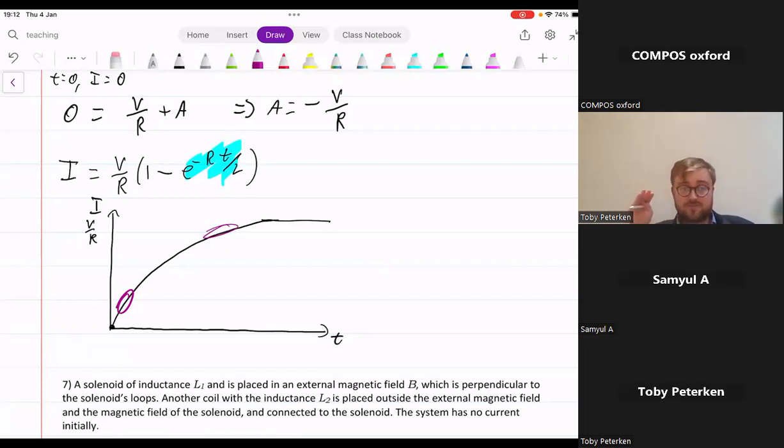It's much shallower. This means the voltage created by the inductor is lower, which means it cancels less with the battery. And so the overall current through the circuit can be greater. So this is what I was saying earlier about how an inductor opposes a change in current. If the current's massively changing, it creates a voltage so that there's no current at all. When the current is steady, the inductor does nothing.